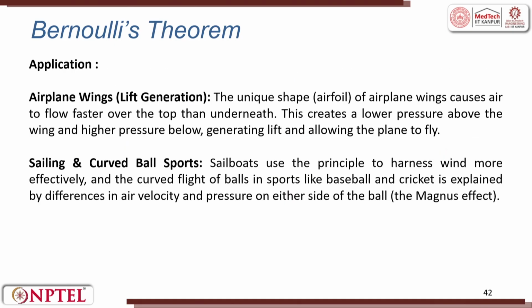So, the applications are aeroplane wings. Lift generation is by Bernoulli's principle. The unique aerofoil shape of a plane wing causes the air to move faster over the top than underneath, which creates lift. This creates a lower pressure above the wing and a higher pressure below the wing. Lift is given to the plane such that it goes up.